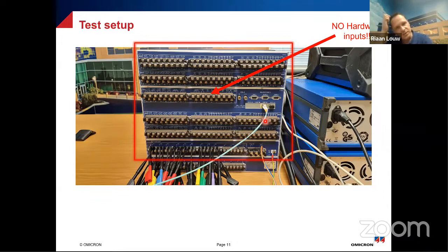Okay, so why are we doing this today? The concept behind this is to show you guys how RelaySimTest can support you in testing not just a simple bus-zone scheme, but also something like an 18-bay bus-zone scheme, where yes, you would have hardwired tripping signals and you would have hardwired inputs, but if you in parallel add logic to the relay for testing purposes, and this logic is a virtual logic, which is GOOSE. If you're making use of that GOOSE in parallel, you can then switch between the hardwire logic and the GOOSE logic, and thereby test the full bus-zone system without having to wire all of these inputs and outputs just to test.